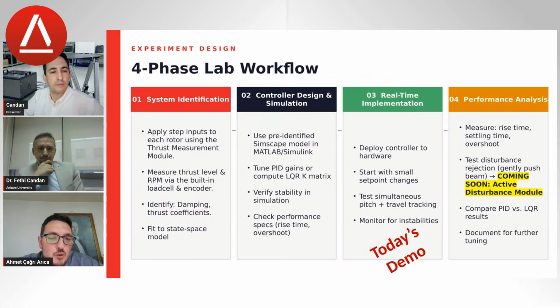There are some differences between simulation and experimental work, so it is very important for the test setup and performance analysis to measure rise time, settling time, and overshoot, test disturbance rejection, and compare PID and LQR results.